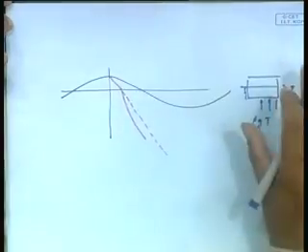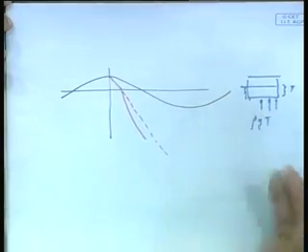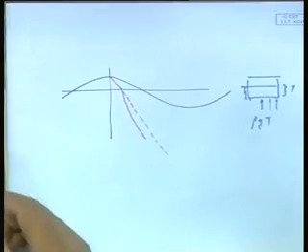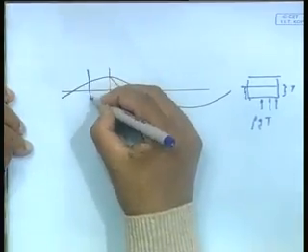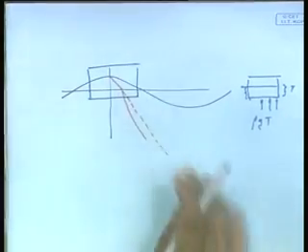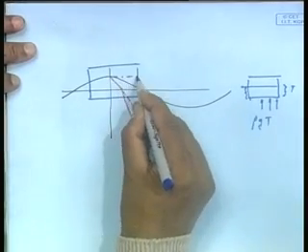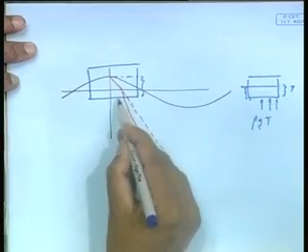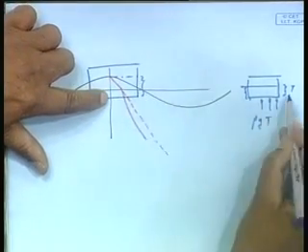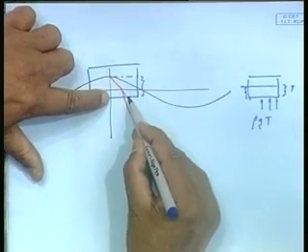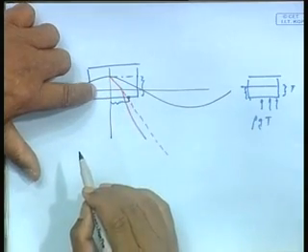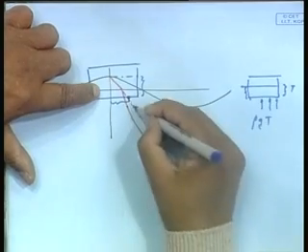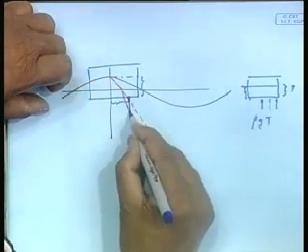It is a flat bottom plate, because obviously I must have as much draft here, because only this face is contributing to my buoyancy in this case. Now here what has happened, I have this body. Now you see here, in this case my draft here is this much, but my pressure, this is my T and this is my rho g T, this much. So if the pressure was this much, my draft would have been T, but actually my pressure is only the small line. So my rho g T pressure would come when this bottom surface is here,